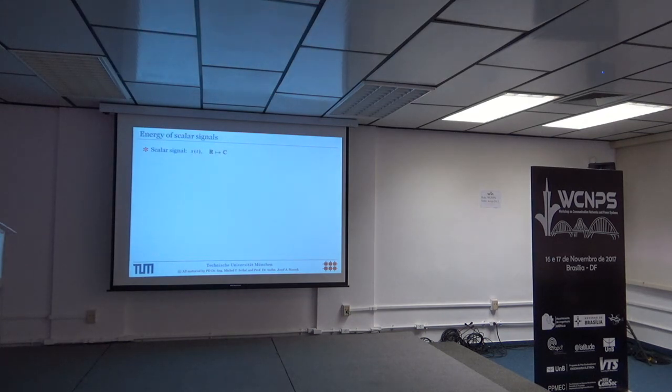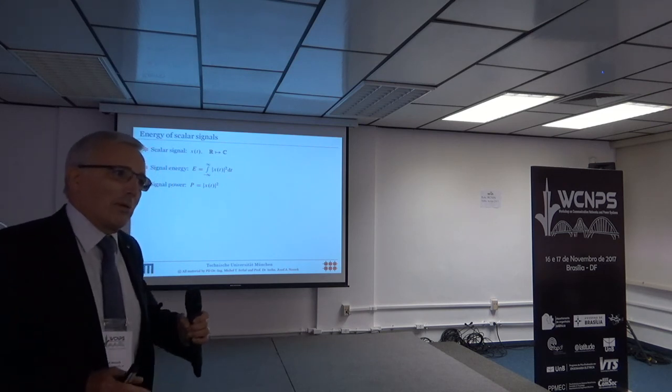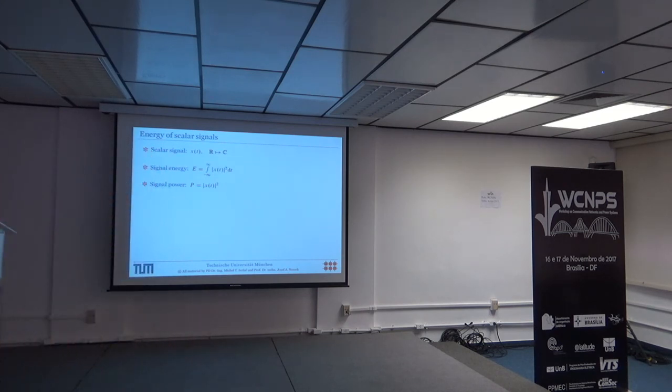And it has also to do with the way how we compute the energy. When you look in a signal processing or communications book, you will find there that the signal energy or signal power is defined basically always by taking the squared magnitude of some complex numbers. And these complex numbers normally don't have any unit. There is no volt or ampere or watt coming with that. It's only a number. Is that a useful definition of energy?